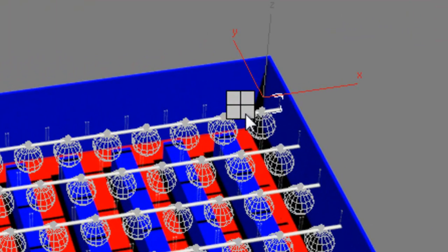And here's a tricky thing. When you export from Revit, the lights get exported separately as an object and photometric data. So you can see here the small white thing that looks like a pendant hanging down from the ceiling is the fixture object, and the web is the photometric data.